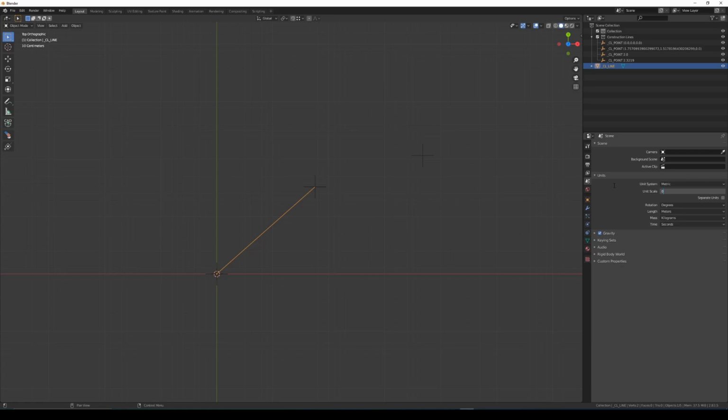So anything you type in here, you might type 0.001, and that will be the scale that is used now instead of this length scale. But measurements will still work with the length unit. I won't demonstrate this, it takes a little while to set up, but if you work in this way you'll know what this means and it will be useful to you in 3D printing or working at a very small scale. So that's a new preference that's been added to overcome this issue here.